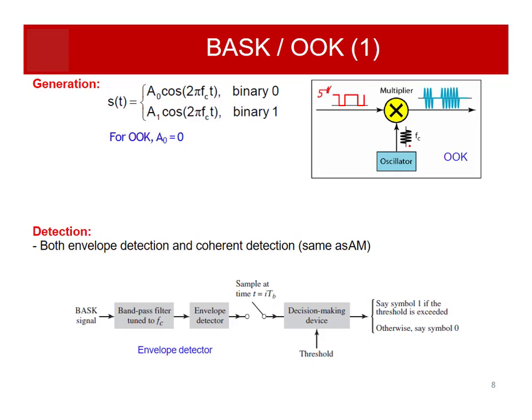So when you are multiplying this with a cos wave of a particular frequency fc, at the portions of this red signal where the amplitude is 5 volt, you will get some output of that particular frequency. The frequency is fc here because this is the input frequency. But the portions where the input signal is 0, anything you multiply with 0 will result in 0. So you will see null here.